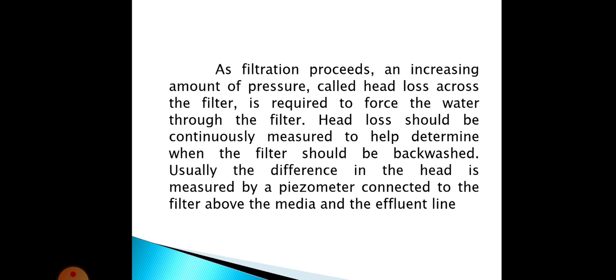We know that as the filtration proceeds, there will be an increasing amount of pressure in the filter unit, which we call the head loss across the filter, and this is required in order to force the water through the filter, or to allow the water to get filtered. And this head loss has to be measured continuously because this is needed to determine when the filter has to be backwashed or when the filter media has to be cleaned.